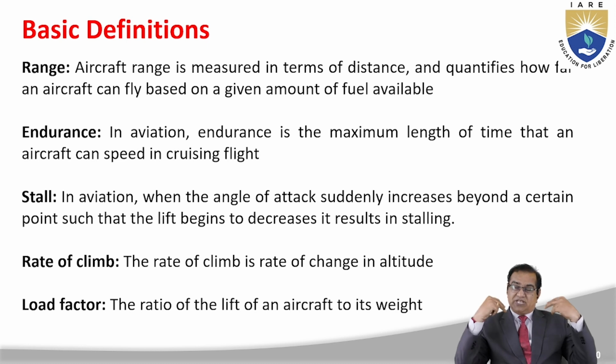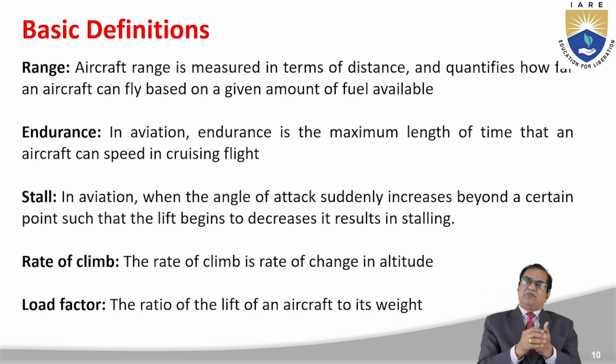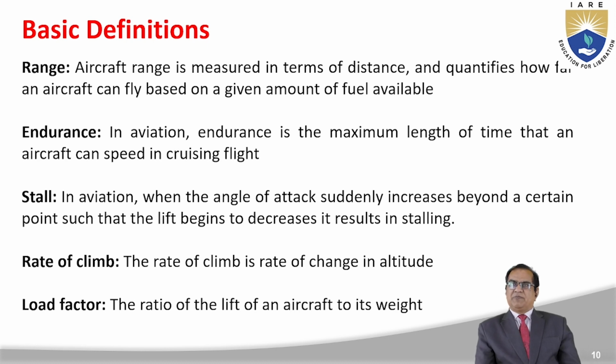But as and when you increase further, then lift will not increase, but it starts decreasing. That point is called the stall point, and we should not go beyond that point. In fact, from there some 15 to 20% below, we have to fly. In case of emergency, in case of some sudden gust and all, we should be able to control our aircraft for this purpose.